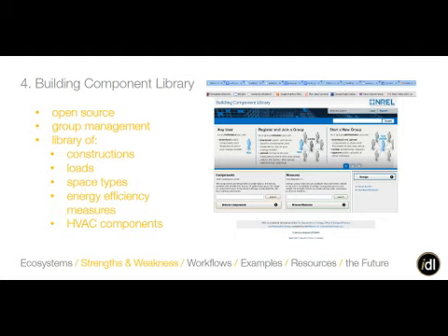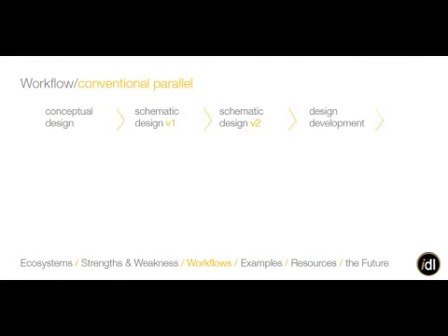Before, you could only really download the OSM file and then manually import it into your model. With version 1, it links directly to it, so you can actually download an LED lighting measure with daylight harvesting into your model and run it directly from this interface, versus having to script and edit everything up front. Also, it's a good team management structure. You can set up a group and start to share files and work from there. So this is going to be a big deal moving forward.